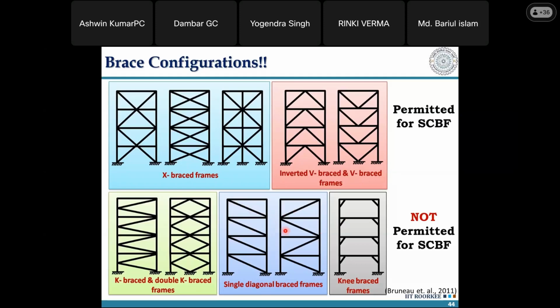And one more thing you have to understand is key. One important thing is while designing, yes, we talked about lateral forces being considered, etc. Under gravity, you have to ensure, when you design, let's say, a chevron arrangement, under gravity, dead load and live load, you have a combo of 1.5 dead load plus 1.5 live load. You have to understand that these braces at one point in time after an earthquake are going to get damaged. One brace might be totally yielded and it may fracture at a later point, and one brace might be totally buckled.